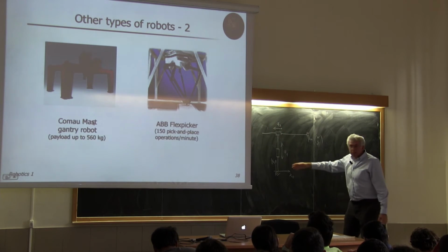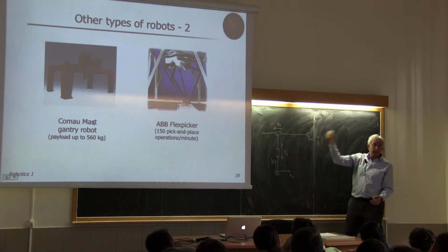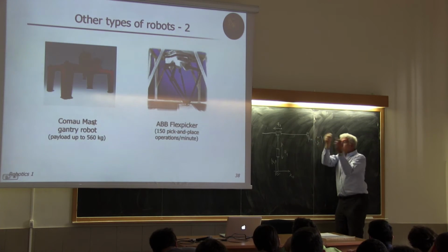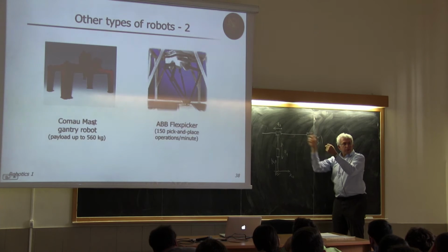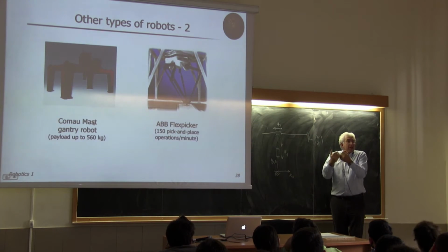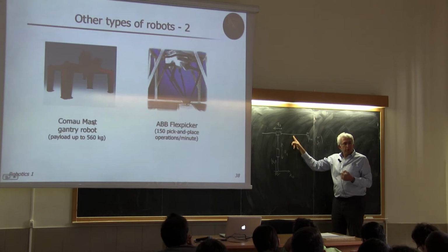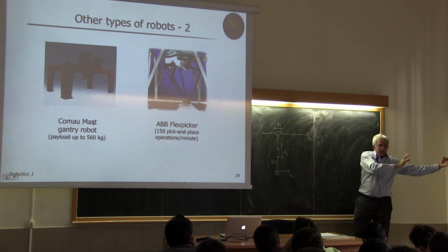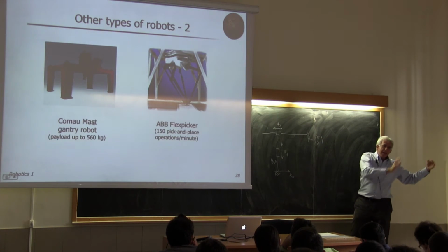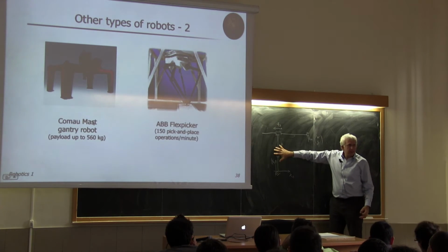So in fact, there is a clear series. Now first Q1, then Q2, then Q3. In fact, if I'm moving Q3, Q2 and Q1 are not moving. So they are clearly preceding this link in the series. Okay? If I'm moving Q2, Q3 is moving, the link connected to Q3 is moving accordingly, but this is not moving.